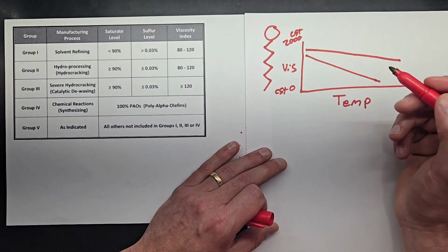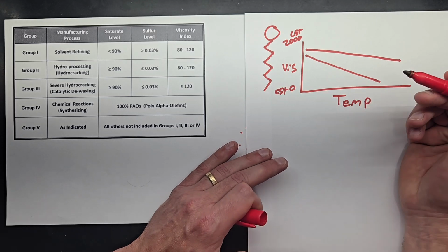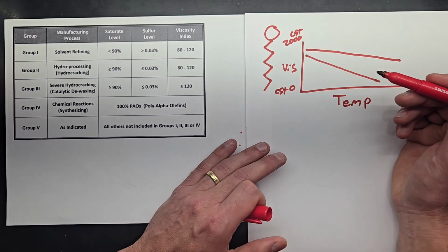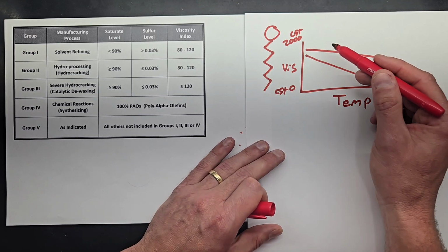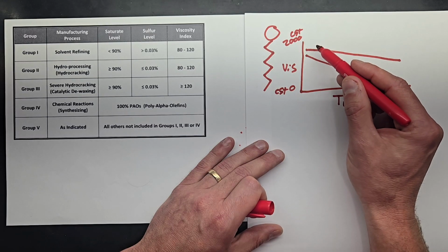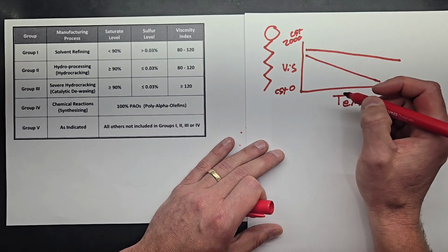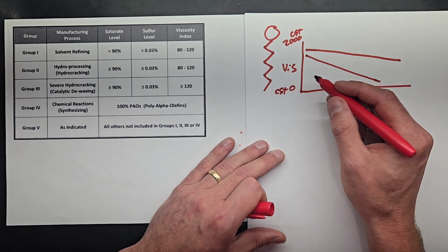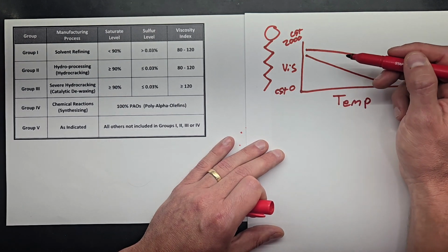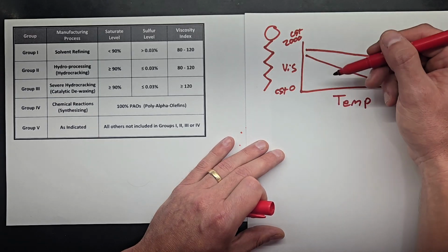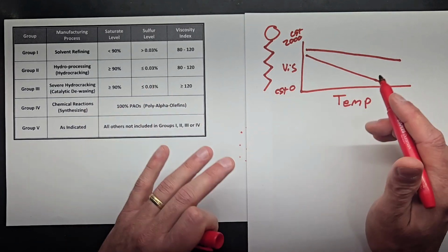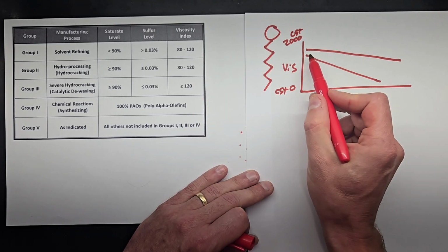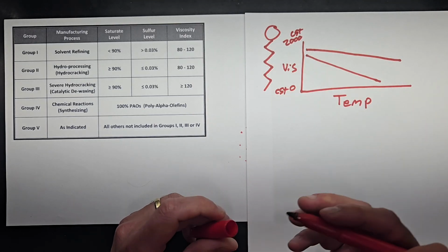And so they defined early, 1900s-ish, one base oil as having a viscosity index of 100, and then I think they defined another base oil as having a viscosity index of 0, and then you're actually ratioing the difference between the two. But for simplicity's sake, viscosity index lets you know how flat that line is.